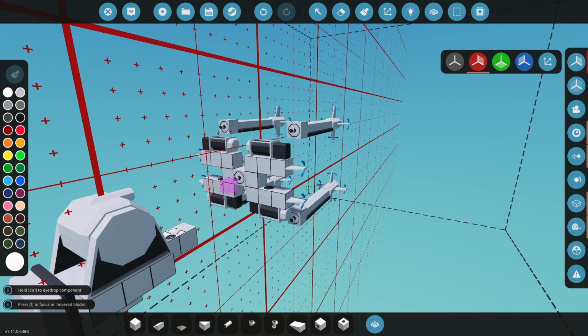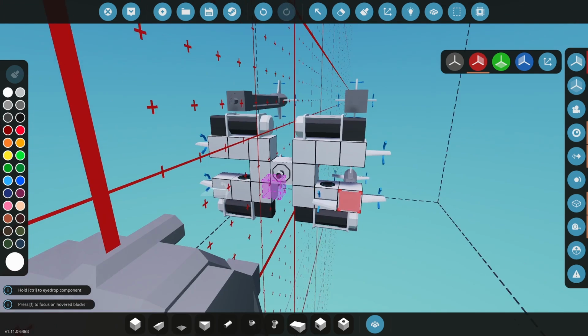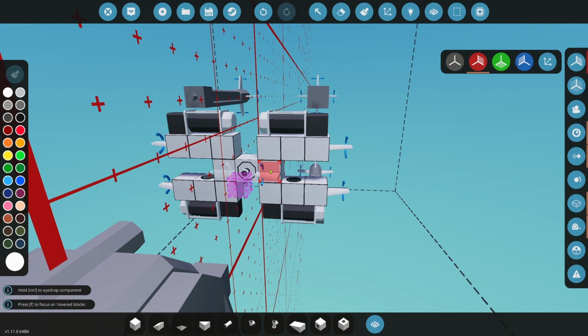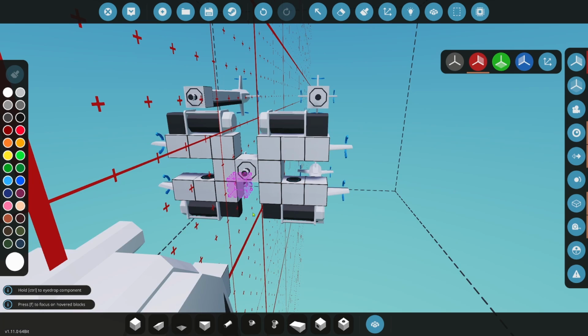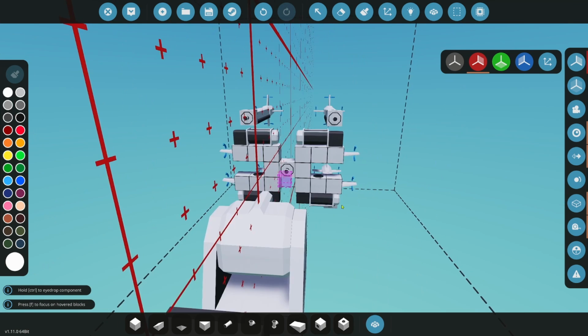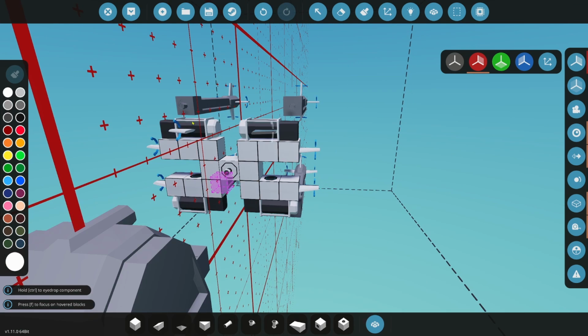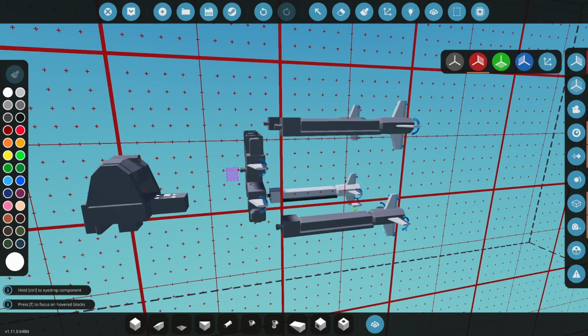What these fins are going to do is when it hits the water, because it has fins, they're going to be less likely to spin. As it tries to torque or spin, the fins are going to fight that. They're going to try to maintain their position. They have static stability, and that static stability is going to keep them from trying to rotate. So I add those on there so that this has less of an opportunity or a desire to spin on us and cause tangling. All right, really cool there.